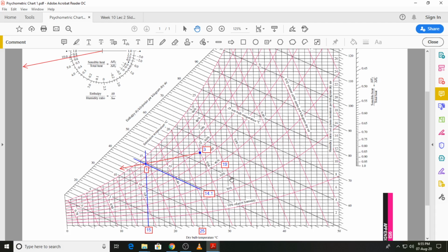And then we had performed the energy balance to find out the volume flow rate entering the room, and to do that we required the values of the enthalpies at states 3 and 1, and also the specific volume at state 1. I will move on to those values of enthalpies, then I will come to the specific volume.